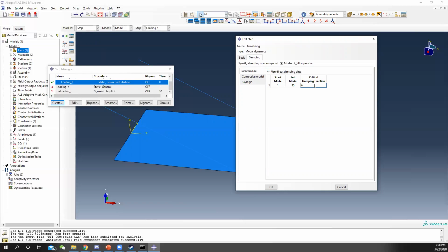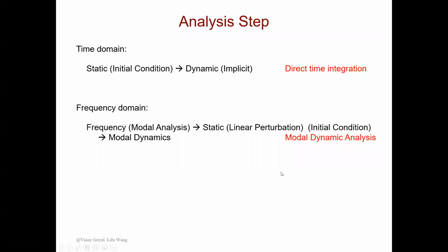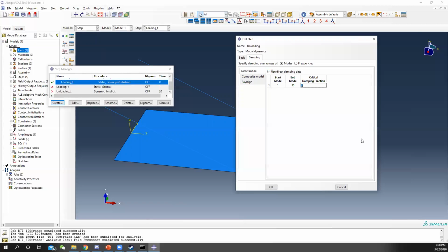First, we do the undamped model, without damping. Normally higher modes will have larger damping, but here we just assume all of them have the same damping coefficient, which is 1%. Now it's 0% because it's without damping.